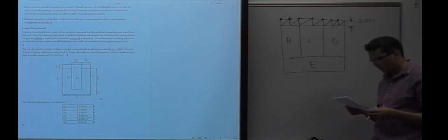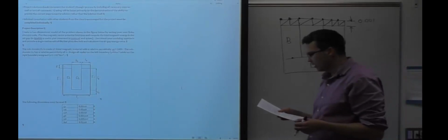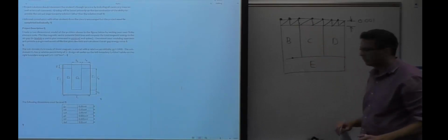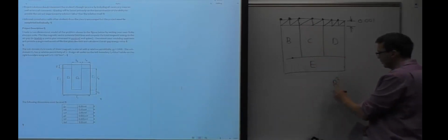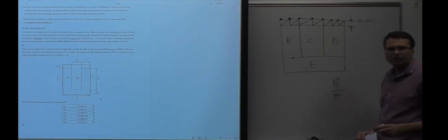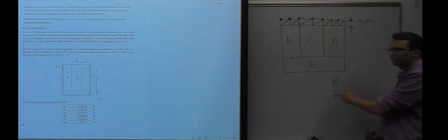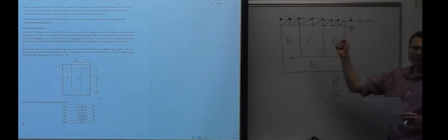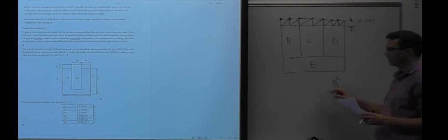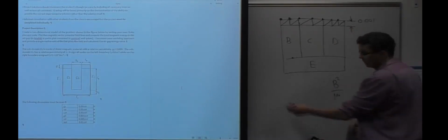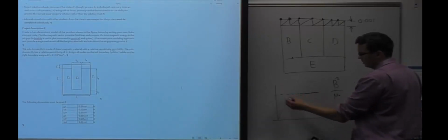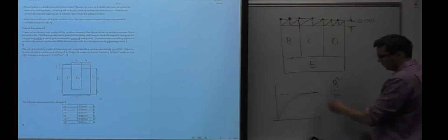And so you need to calculate what the energy is in the air gap. Remember that B squared over mu naught gives the energy density. So you can use this relationship to calculate the energy. As you increase the number of elements, your value for your energy should not keep going up. It should become some constant value as you increase the number of total elements in the code.